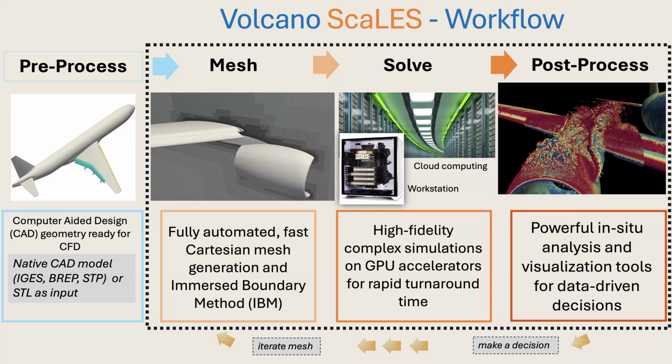to the aeronautical engineer or CFD scientist who is familiar with the flow, if it's a high-lift system. For example, if a chine vortex is not seen and the CFD technologist is aware of that kind of thing, they can put in a block and come back to where they stopped, add that block, and the solution is interpolated from the previous case, and then he or she can continue running. So this whole thing may take 3 to 5 hours, optimizing the coarse grid.